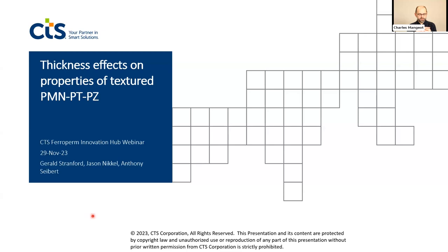So there are limitations in terms of which materials can be processed for texturing. There are, and I would say it's not well understood, the interaction between the template particle and the matrix as far as when you can drive texture and when you can't. So we have primarily focused on materials that we know single crystals can be processed from, because we know they have a tendency to want to texture when single crystals are easily made from them.